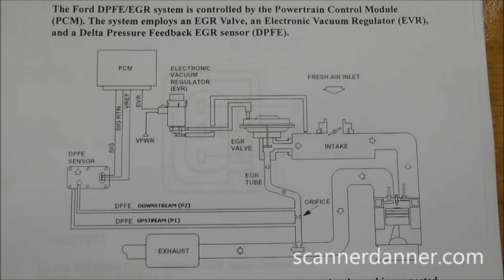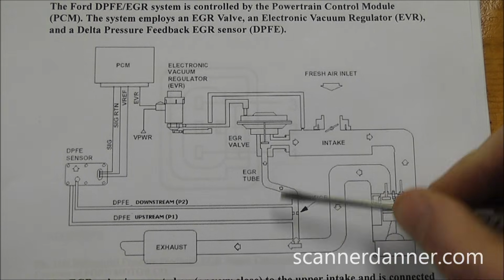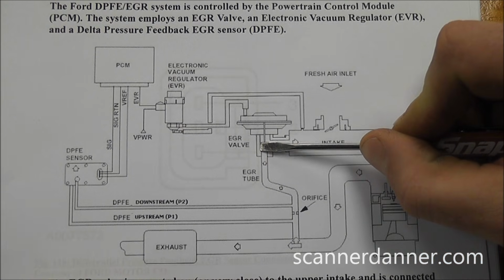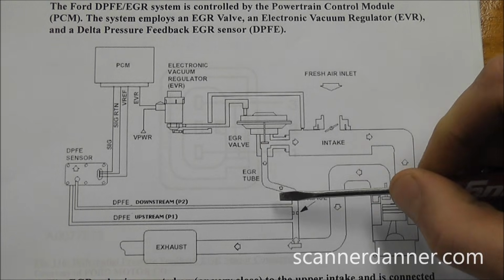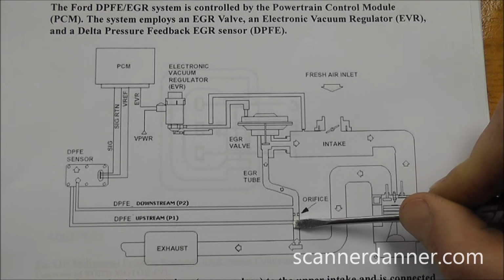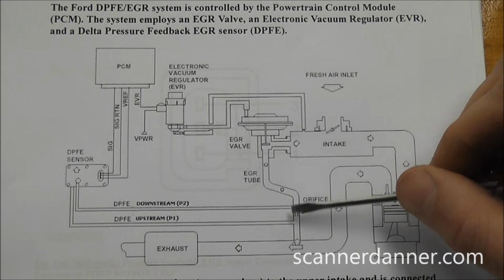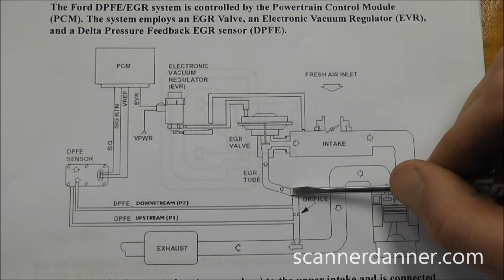The number that I use in my book for you guys, generally between 0.5 volt and 1 volt at idle with the EGR valve closed, is pretty standard across the board. So no change in pressure between these two means the valve is closed. That's going to be key on engine off or key on engine run. That pressure is going to be equal, so it really shouldn't be much different. Very, very slight change from engine off to engine run because the difference in pressure is still the same.